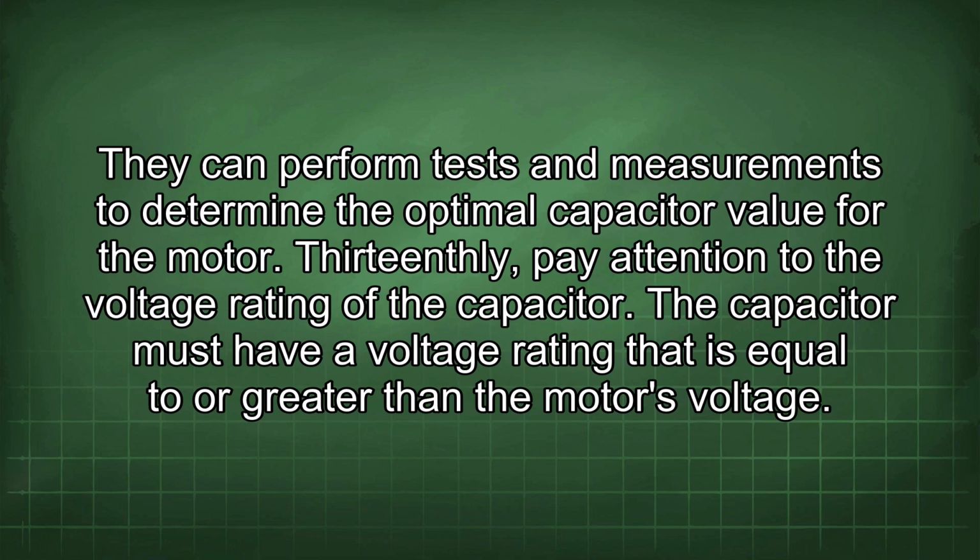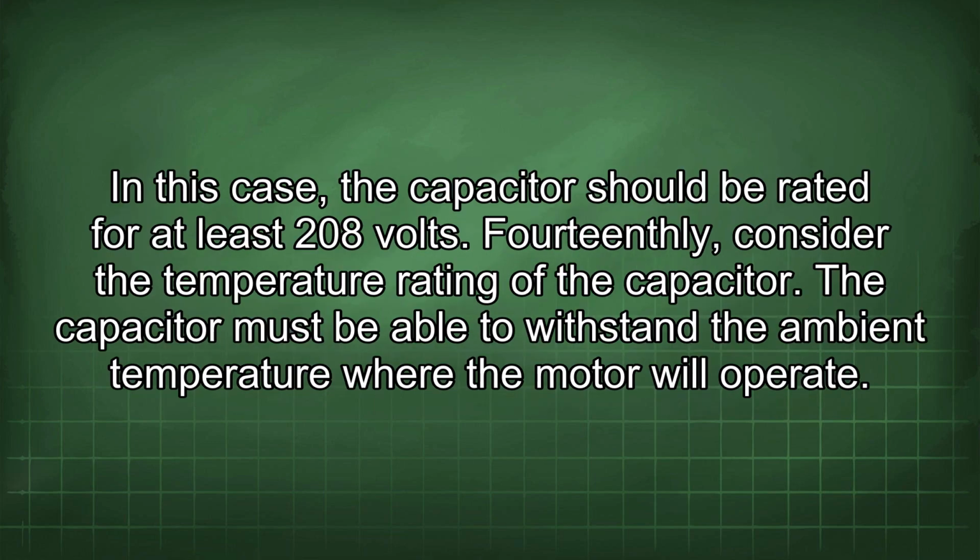13th, pay attention to the voltage rating of the capacitor. The capacitor must have a voltage rating that is equal to or greater than the motor's voltage. In this case, the capacitor should be rated for at least 208 volts.